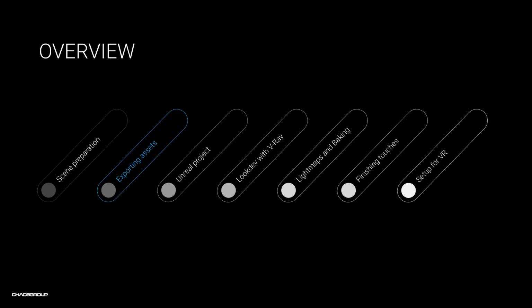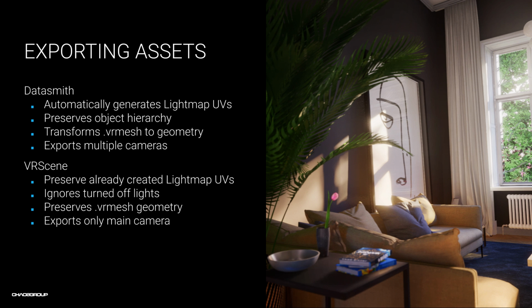Next, let's look at exporting the assets. In order to transfer the scene to Unreal, we can use 2 different methods. The first one is using the Datasmith plugin for Unreal. The second method would be to export a V-Ray scene. For this project, I'll demonstrate both methods to export my scene.